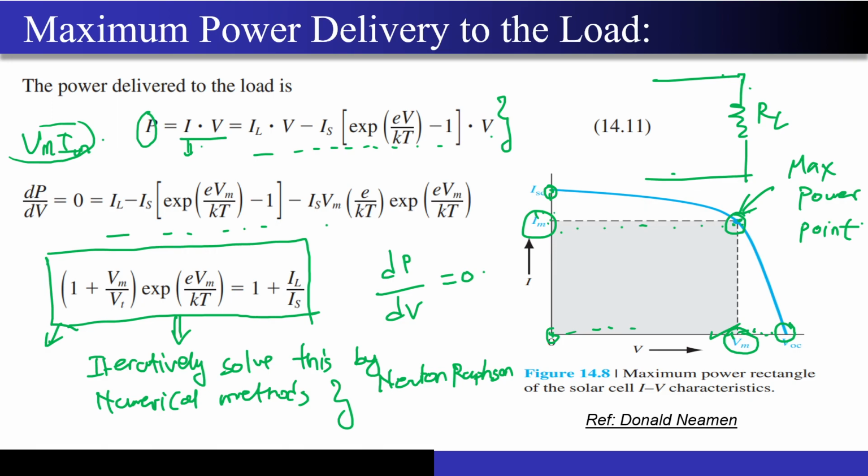So now what this is actually telling you is that this is one extreme of voltage, and this is the extreme of the current, right? If I multiply VOC into ISC, can both of them occur simultaneously? Is it like the moment I have an open circuit voltage of VOC, I will get a current ISC? Of course, definitely not. When you have an open circuit, there won't be any current flowing, and when you have a short circuit, there will not be any voltage, right?